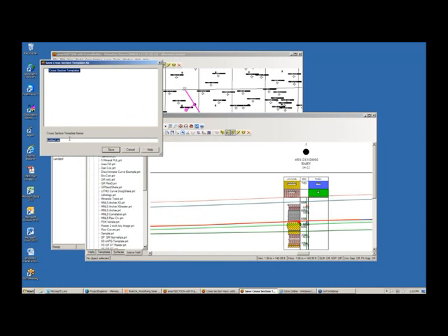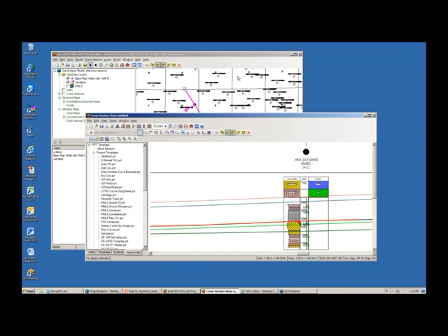And when you save a template, you're going to want to give it a name that means what it does. So in this case, it's a projected straight well template. So whenever I select this template in the future, it's going to be when I'm creating a projected line of section. Your template is going to automatically be stored in the template tab for all future cross sections. So if I come up here and do a brand new cross section, double click on projected straight well, it's going to come up looking like this. Okay, so that is how we make the templates.